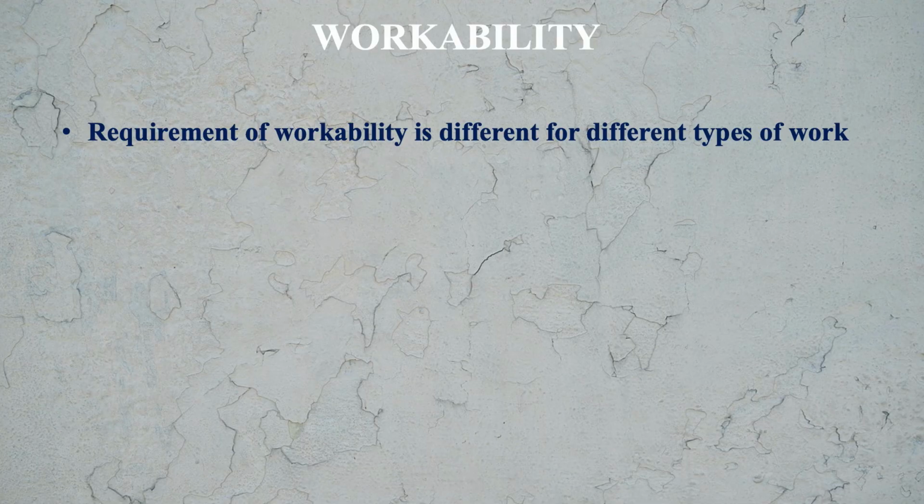The requirement of workability is different for different types of work. If you are doing concreting in a foundation, then the workability requirement will be different. If you are doing concreting in a column, then it will be different. If you are doing mass concreting, then the workability requirement will be different. So the nature of work will decide the workability requirement of the concrete mix.